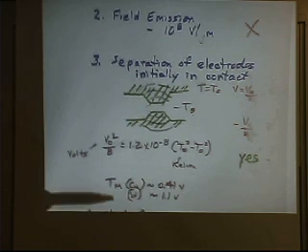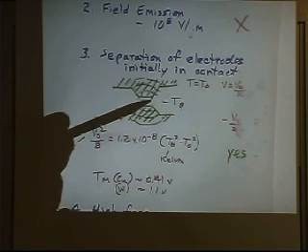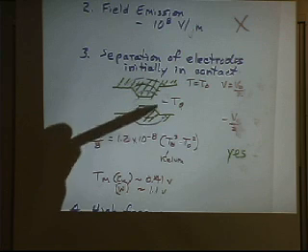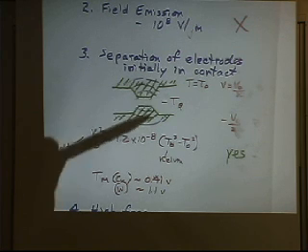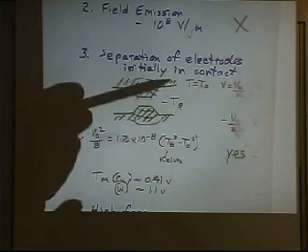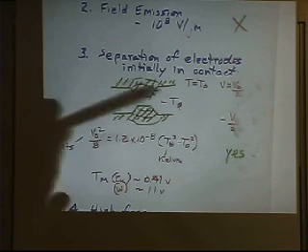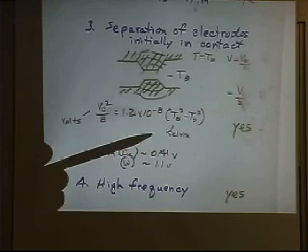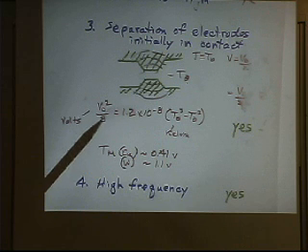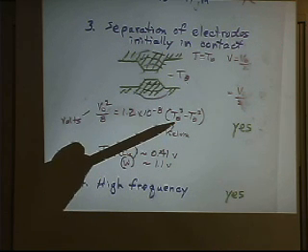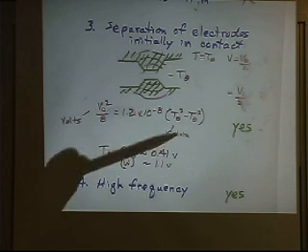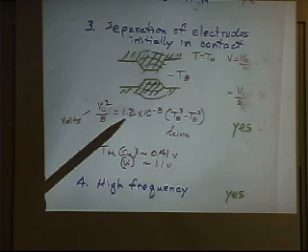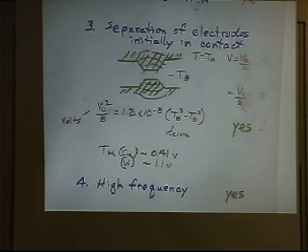It turns out Ragnar Holm worked it out. If you idealize this geometry, and you say this is the interface temperature T theta, and you have some voltage V0 over 2, plus V0 over 2, minus V0 over 2, and you have some ambient temperature, room temperature, you can work out an equation that relates the voltage to the thermal energy, okay? Electron volts are equal to the thermal energy. There's a relationship in here between the thermal conductivity of the material and the electrical resistivity of the material.